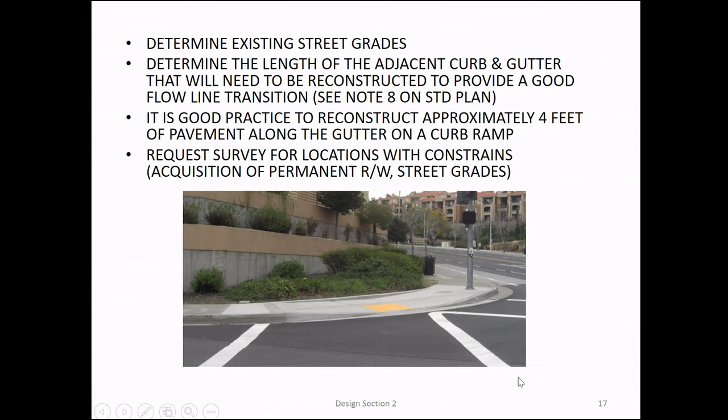And again, like I've said before, make sure you look at this. Maybe it's hard to see, but the flow line goes up, and we're probably trapping water here. How can you get water to flow, though? If you have to raise that so that the gutter's 5%, the other gutter's 8.33% on each side of it, so that gutter has to be raised there. How can you avoid having a high point there? You cannot avoid it, so then your water's not going to flow.